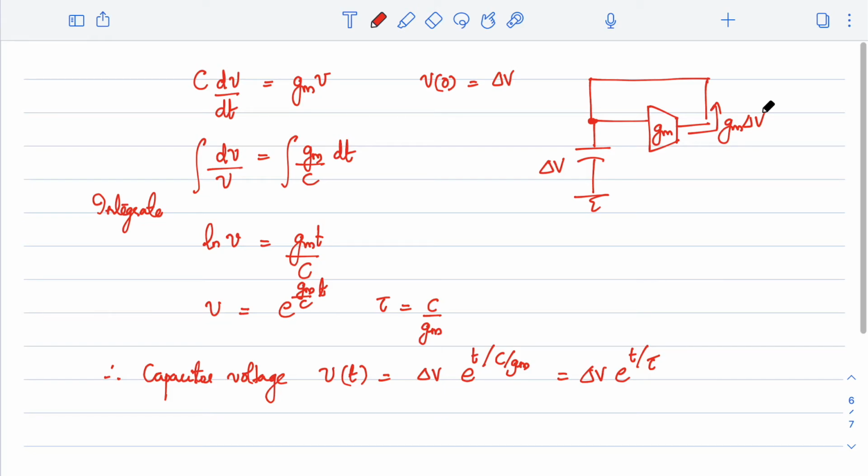All right. Now, if I can write the capacitor voltage in this form, it is obvious that this is actually a first order system, right? For this first order system, can you tell me what will be the pole location? What is the pole location in this case? First order system means you have a single pole, one time constant that will give you one pole.